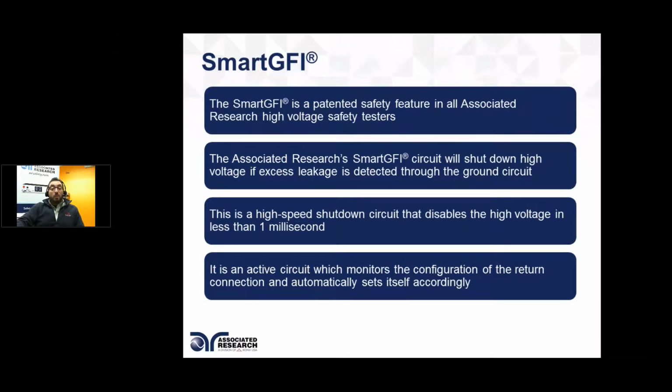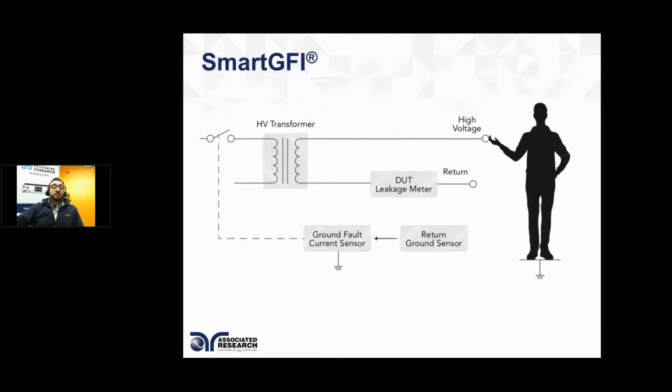Now again, remember that this is more geared towards protecting the operator, but what we have seen is that the Smart GFI also comes into use in determining whether a product is leaking to ground or not. If a product is somehow not grounded, but we think it's not grounded, and we're testing it, and the Smart GFI is enabled in the HiPod tester and keeps tripping when you perform the HiPod test, it keeps failing for Smart GFI. Well, there's something somewhere in the device under test that's leaking to ground, and that gives us something to look for on the device under test.